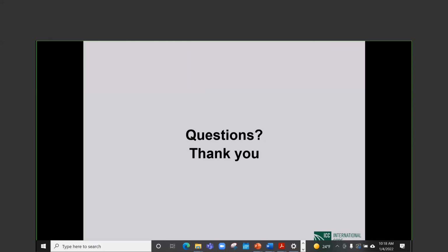So the other question is related to the webinar. What should be the ideal design life of a building if BNBC is followed minimally? Yeah, the question is framed in a good way. I do not know if there is a definite answer to that question. Maybe Dr. Rakib has an answer, but we typically assume the service life of a building to be about 50 years. This is a typical expectation. If you comply with BNBC 2020, you should expect a service life of no less than 50 years. Obviously, if it turns out more, it is fine, but it should not be less than 50. This is not written any place, but this has been our expectation over the years.